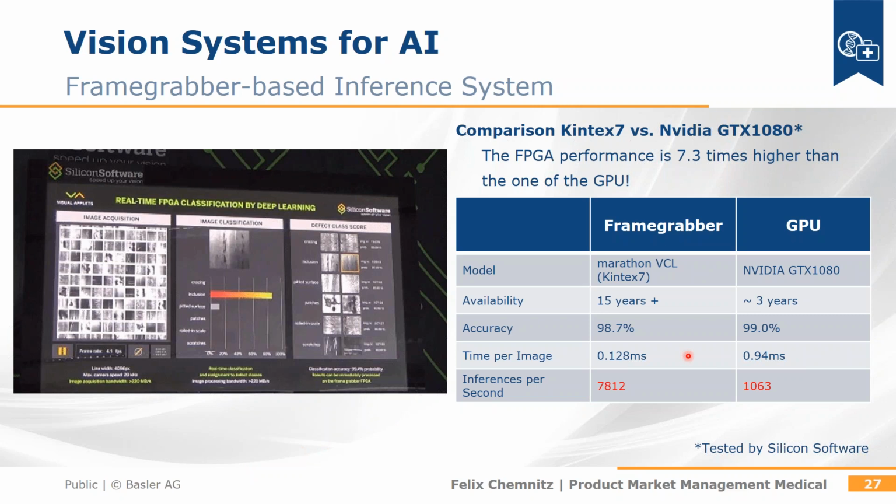benefit, because, as my background is from the medical field, we always deal with certification issues. And if you need to change your GPU, for example, in a system after maybe 3 years, or let's say you designed it in at the height of its life cycle, you will get it for maybe 1.5 or 2 years. After that, you need to take a new one for a new product. You need to go through recertification in this medical field, and this would lead to a lack of products in your portfolio. So it's easier to go with the frame grabber, which is available for more than 15 years in